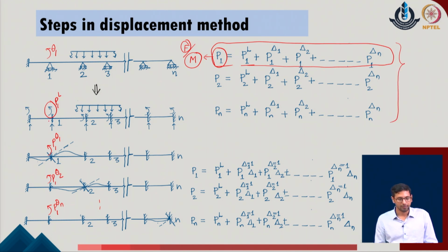As we have already seen earlier, corresponding to each of these loads, each of these forces which we are describing, we first consider a unit amount of displacement or rotation to take place in the given system, and with respect to this unit value of the displacement, we define this condition as the stiffness of the given problem. So, we have defined this condition, say with respect to P, the force in the direction of degree of freedom 1, with respect to the unit displacement in the direction of degree of freedom 1, and we call it S of 1 1. Similarly, this is the force in the direction of degree of freedom 1 with respect to the unit displacement in the direction of degree of freedom 2, and we call it S of 1 2 in the given system.